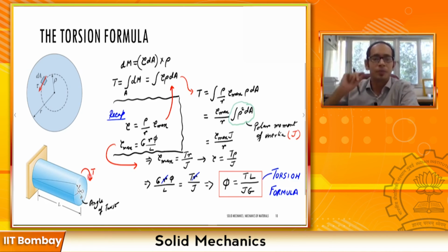It is not as straightforward as some of the expressions that we derived before, though we will see later they're analogically similar. But remember, for the axial load, delta equals PL by AE, we got it in a jiffy. It was very easy and quick to derive. Whereas here, to derive this fundamental relationship, we first had to start with the strains gamma. We went to the stresses tau. We established the relationship between tau and T over here, this particular relationship, right?